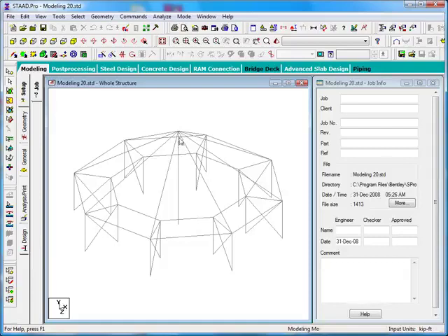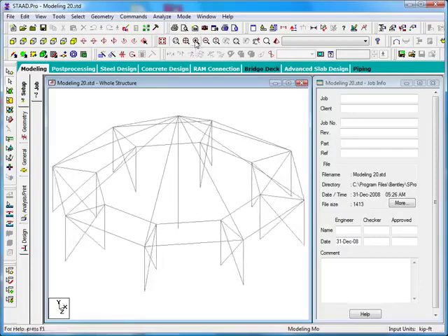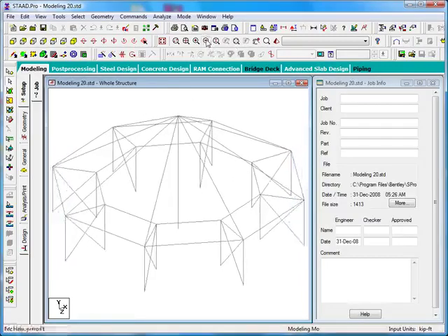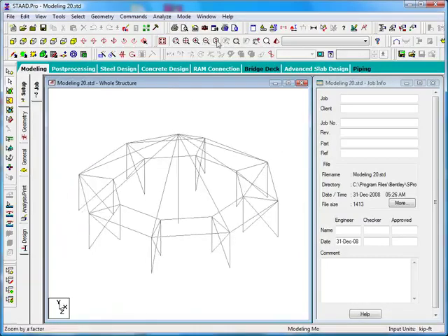We'll see how to turn off selective elements in a step or two here, but what zoom extents does is it returns the structure to the isometric view and it resizes it to the maximum size that'll fit within the main window, but it will leave off any elements that have been currently turned off. In addition, we have the obvious ones like zoom in, which zooms into the structure a set amount per each click, and a zoom out button that zooms backwards.